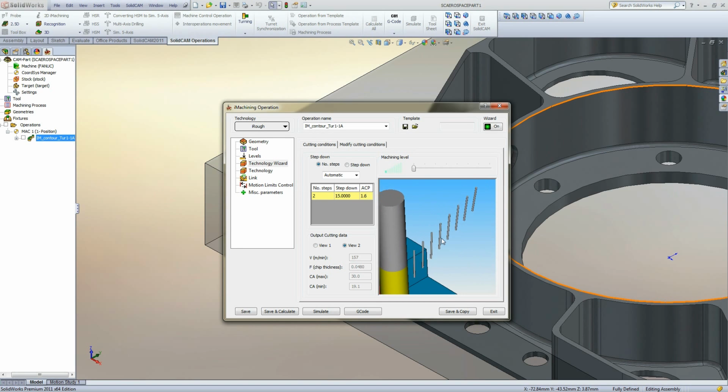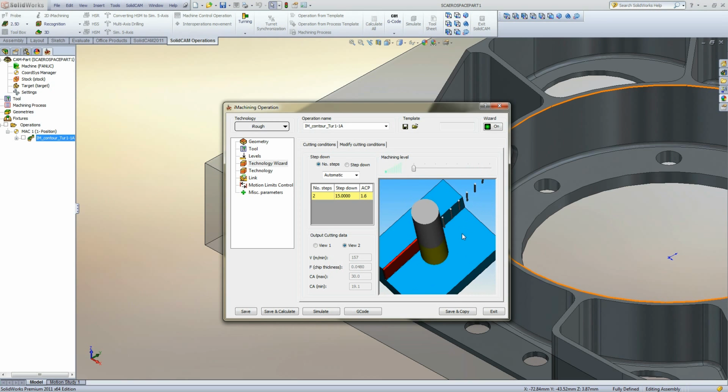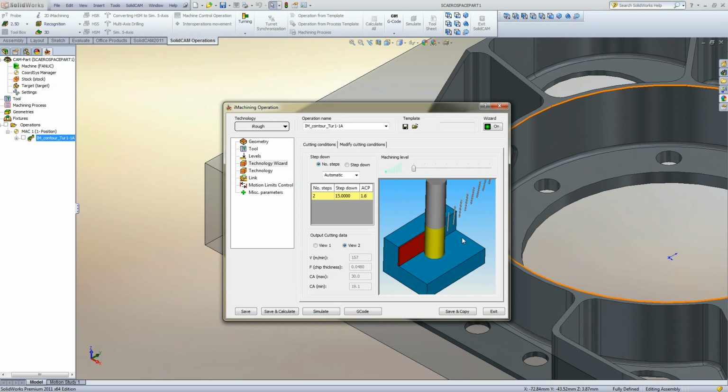The 3D chips change color, quantity, and size to show that moving up in milling levels produces thicker and more chips with greater heat. Also, the 3D preview window shows how the chips should be evacuating the cutting area under good conditions when actually machining the part. The chips should be coming out the back of the tool. If the chips are sticking to the tool due to heat and are being brought back into the cutting area, the potential for failure is high.